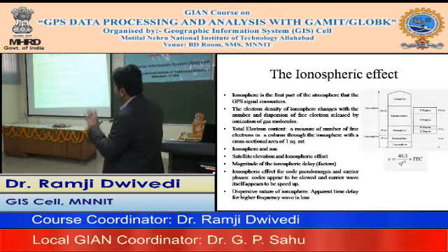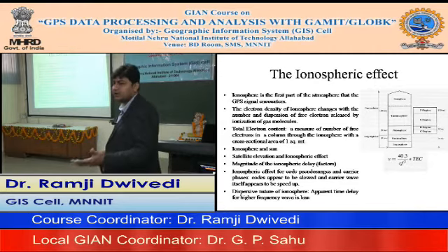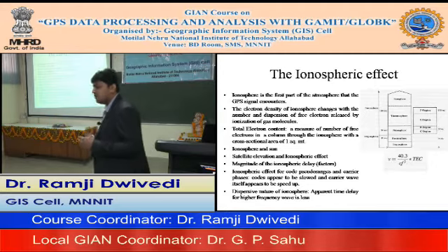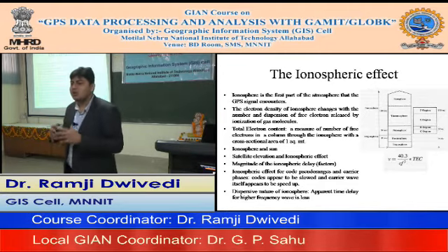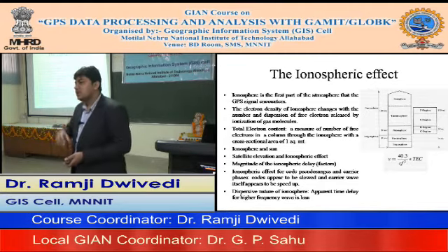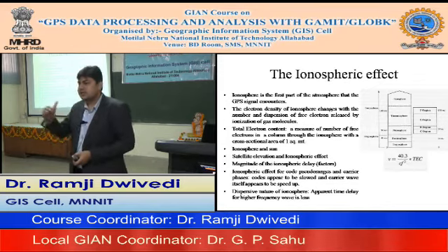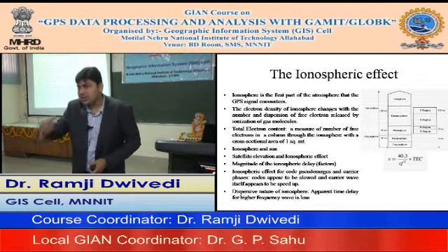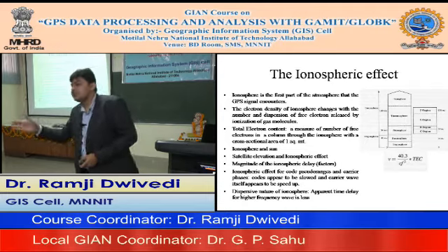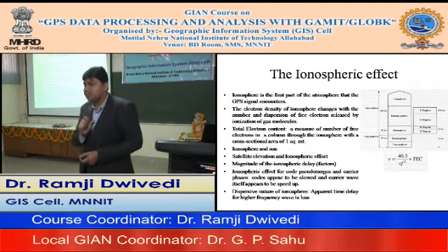So the ionospheric effect can be removed because of this dual frequency nature, and that's why the quality of estimates improves. However, when you use this combination, we are only reducing the effect, not totally removing it, isn't it? It depends to what extent you are reducing it. That's why the new strategy we popularly use is DGPS.